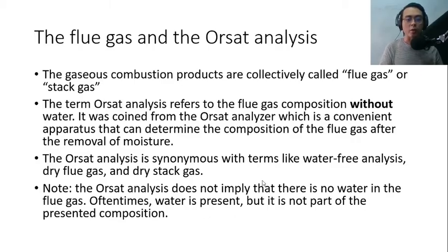This is just highlighting what I have said earlier. The Orsat analysis does not imply that there's no water in the flue gas. Oftentimes water is present, but it's just not part of the percentage composition. So you still have to factor in the water. I will be showing this in our computations later.